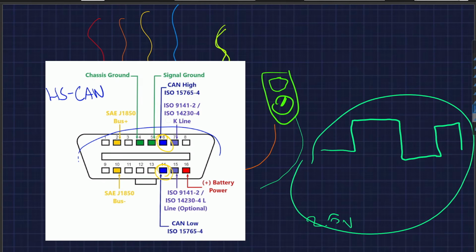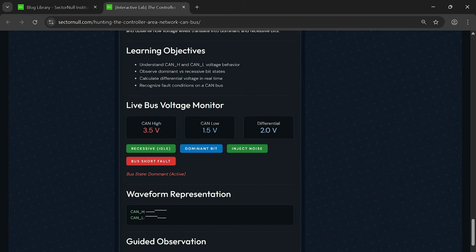And now let us shift to packet structure, because once you can connect to CAN, you will see traffic immediately, and it can be overwhelming. Now, there are two types of controller area network packets you will encounter: the standard and extended. But before explaining that, let's go back. We have covered the dominant bit here. Basically, the differential voltage increases, and this represents a logical zero on a CAN.